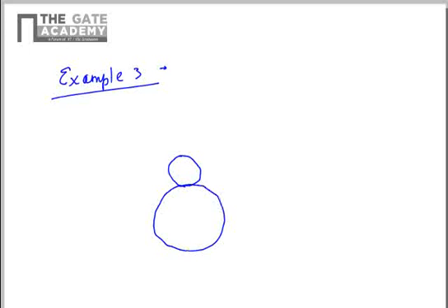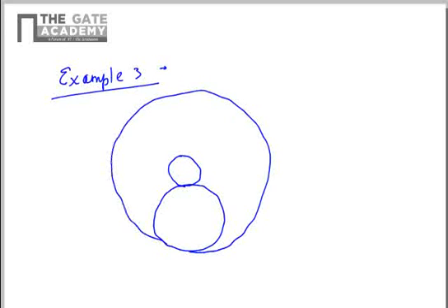Now we will take up another numerical example, this time related to the epicyclic gear train. So I'll draw an epicyclic chain here. We have a gear A, which is the sun gear. It meshes with gear C. This is a planet gear, and C is enclosed inside an annulus. So this is the annulus, and A and C are connected by the leg. The standard epicyclic train. And in this case, they have given a special combination of epicyclic gear train as well as compound train.